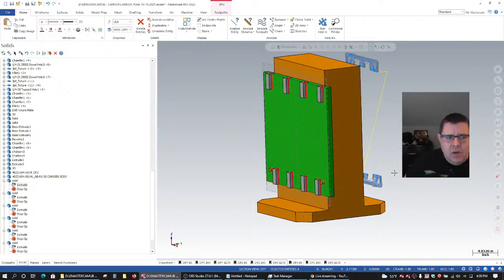So the non-simplified models, if they're not being used, like the complex ones, I would definitely delete them out of my Mastercam file. The other thing you can do, save a version of it as like op10 or op1 or whatever, op1, op2, op3, so that you've got a backup copy where everything is fully detailed, and then create your working file without all the complexity.